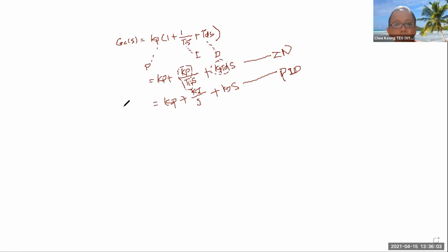Now what Ziegler-Nichols advocates is that we can keep increasing this Kp. You can increase the gain from 0 to, let's say, infinity. And before it reaches infinity, at some point your whole system will start to oscillate, right? He is actually interested in this gain at which it starts to oscillate. That means, okay, when does a controller start to oscillate? At first, you increase your gain.